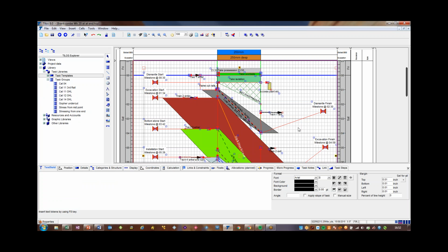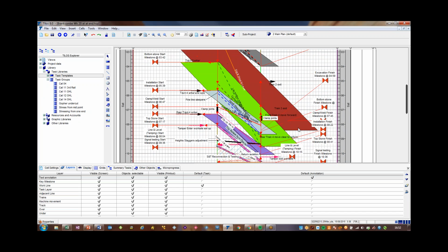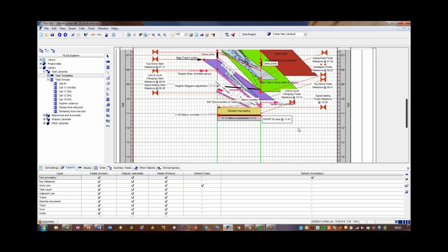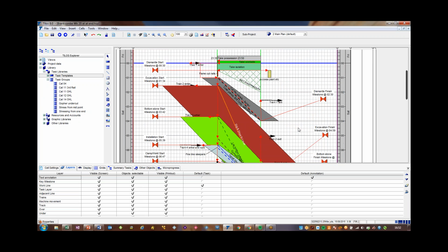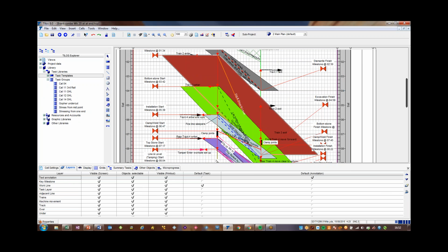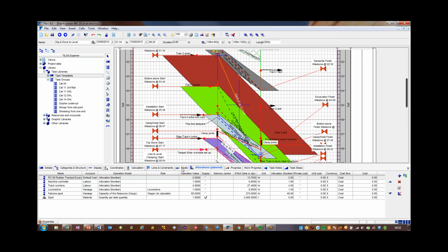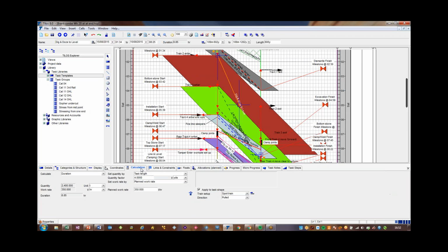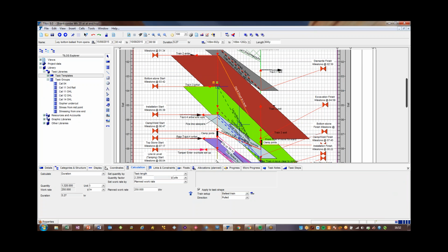And so look, all of those activities are created in one operation because we've created them in advance, all logically linked. So all we've got to do there is say, on the rough dig, we're doing that at 3.37, our ballast calculator says, and if we're laying bottom ballast, we're doing that at 2.2 or something.